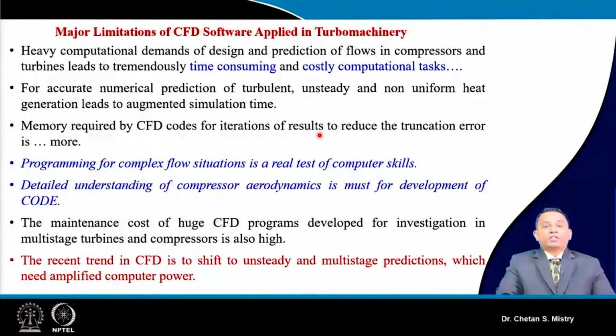Accurate prediction of turbulence, unsteady or non-uniform flow requires an augmented amount of simulation time. We may assume our turbulence intensity for the initial design case, but later on, when we go for performance assessment, we need to be very careful.